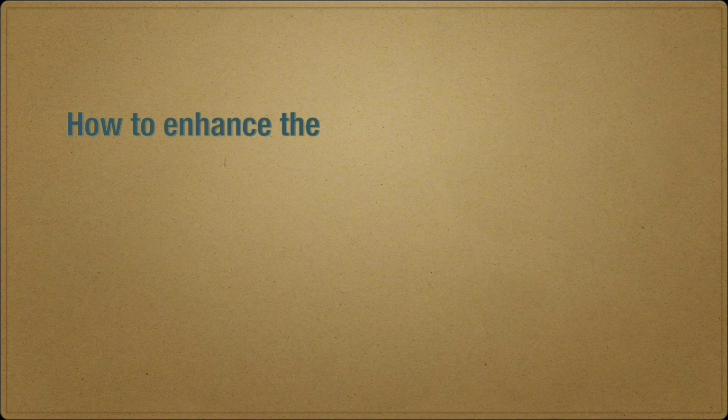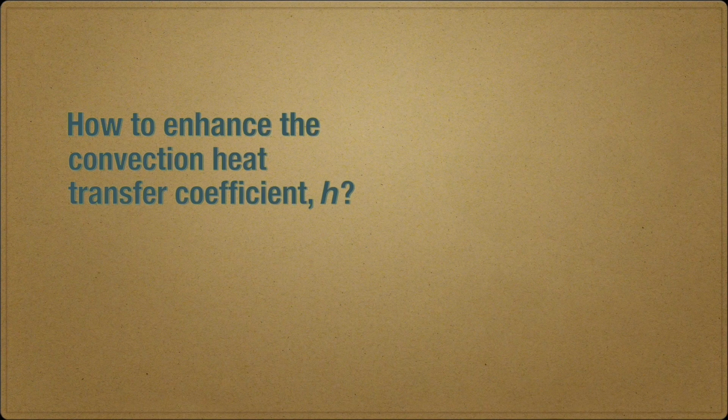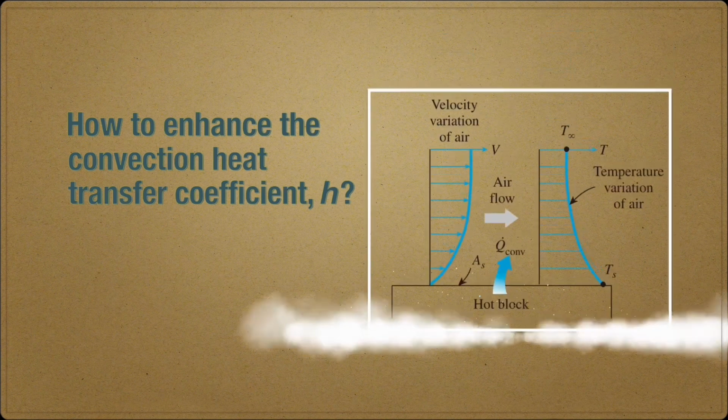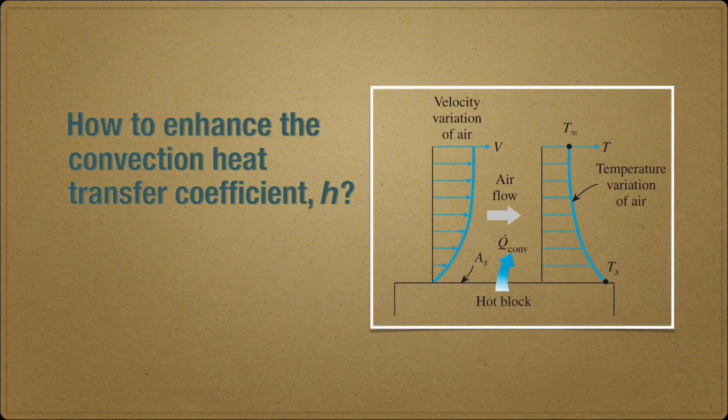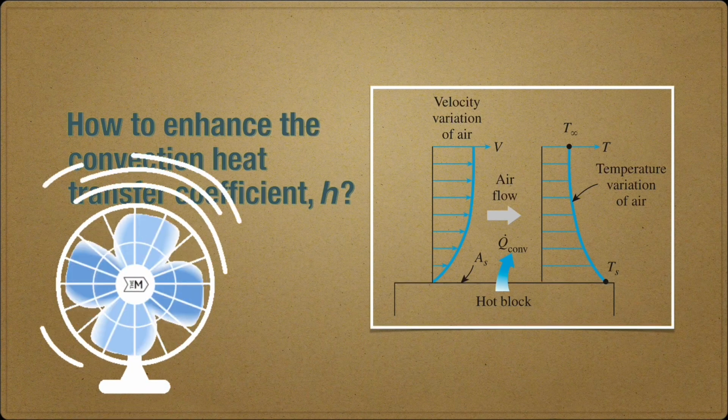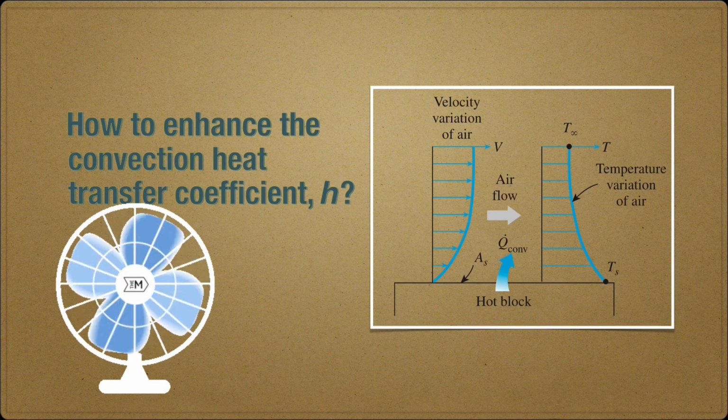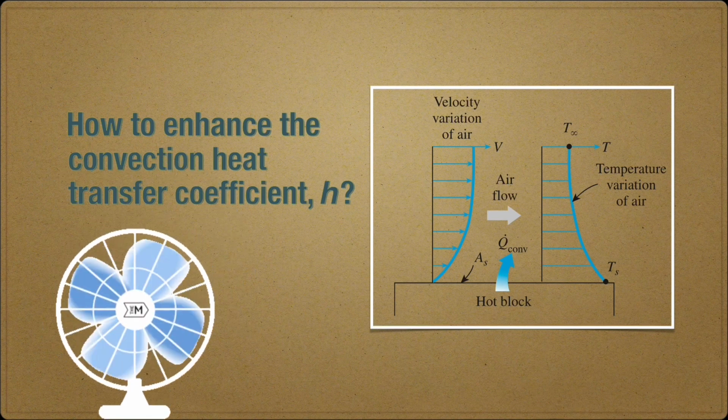How to enhance the convection heat transfer coefficient h? Increasing the convective heat transfer coefficient h may require the installation of a pump or fan or replacing the existing one with a larger one. Still, this approach may or may not be practical.